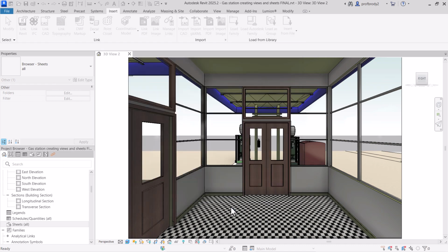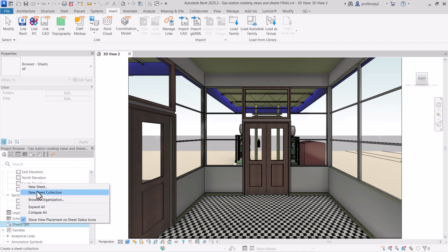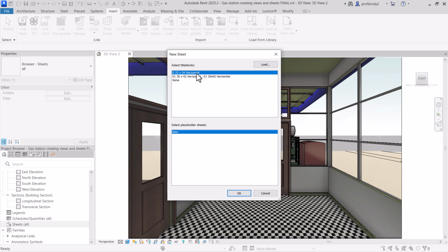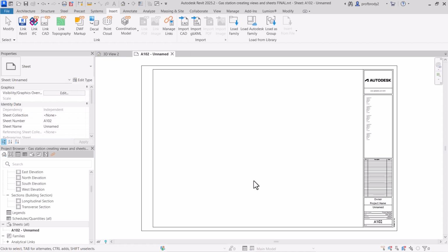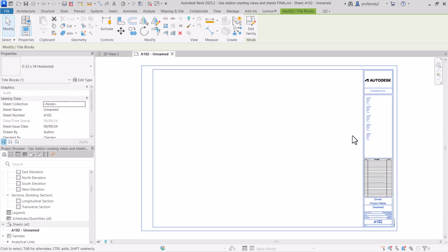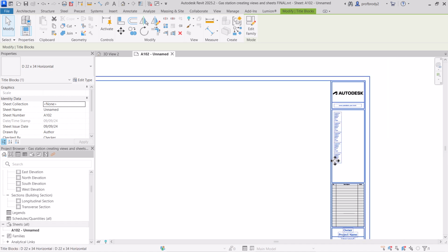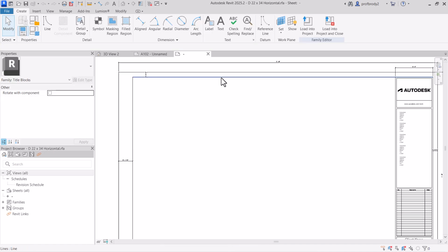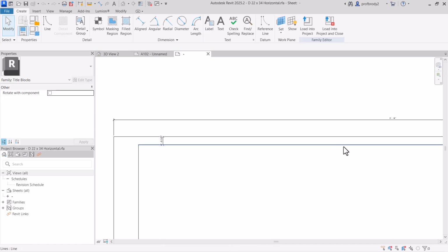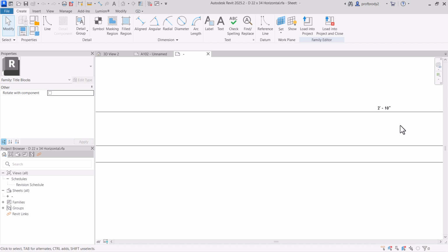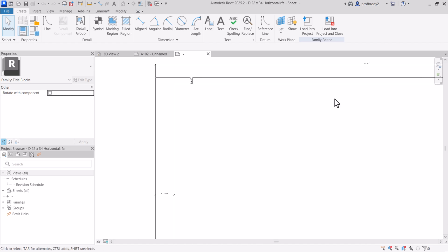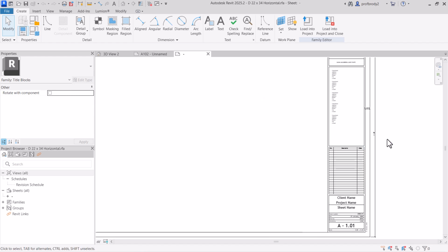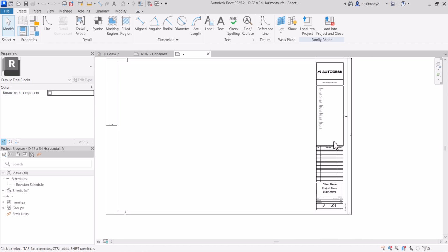The reason that I like to use that is it has some of the text and things in there that's kind of nice. So now when I've loaded that in, I have a blank sheet of drawing. Now, of course, nobody wants to be an advertisement for Autodesk, so I'm just going to double click on this title block, and you can actually get the real dimensions of this thing. So it's actually 2'10" by, they leave a very large border, by 1'10".